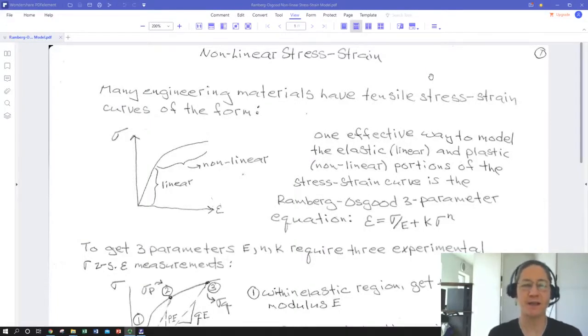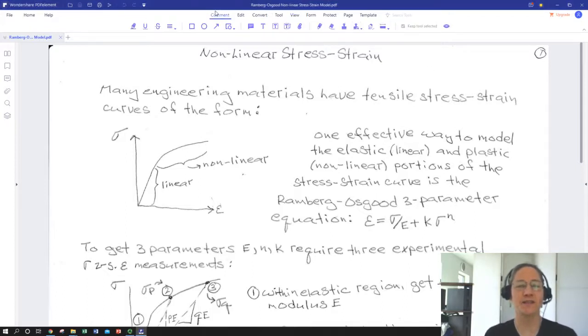In this mini lecture we will be discussing one method for dealing with stress-strain relationships beyond the elastic limit. So to date we've been discussing the concept of stress and the concept of strain. We've introduced the coefficients of elasticity: tensile modulus, shear modulus, Poisson's ratio, bulk modulus. All of these concepts deal exclusively with material behavior down here, where stress and strain are linear.